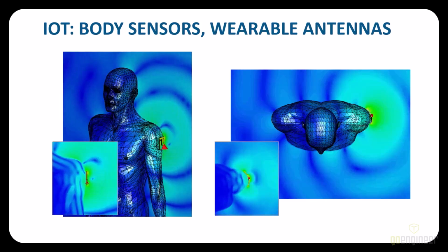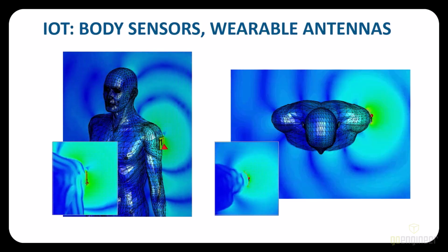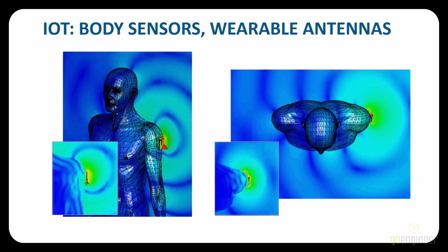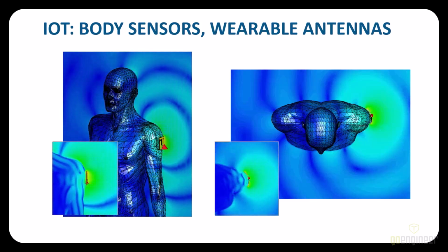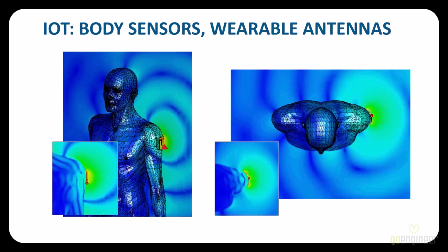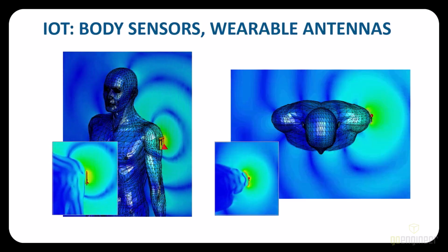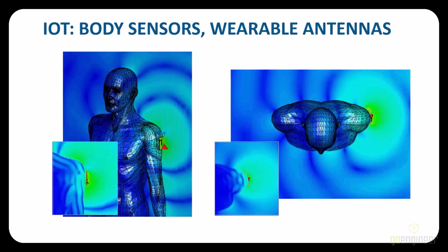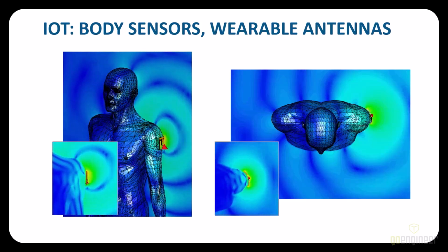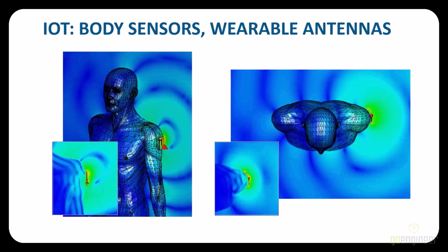We can immediately predict the far field radiation pattern would be distorted compared to the antenna radiating in free space without the human body. You can see the fields induced on the surface along the shoulder and over the head region. These kinds of surface waves could potentially couple to other body-worn devices, such as hearing aid devices, and could cause electromagnetic interference issues.